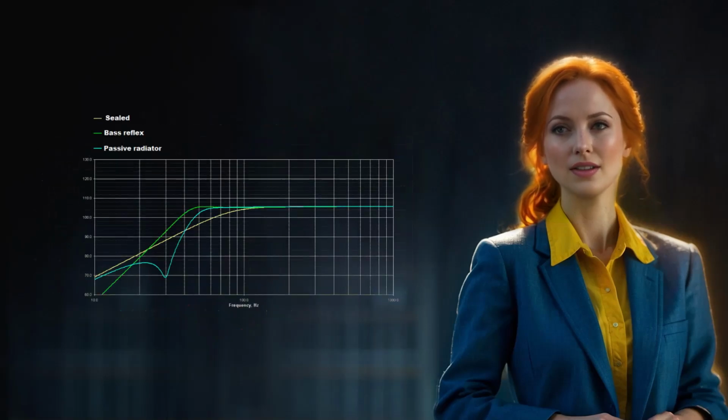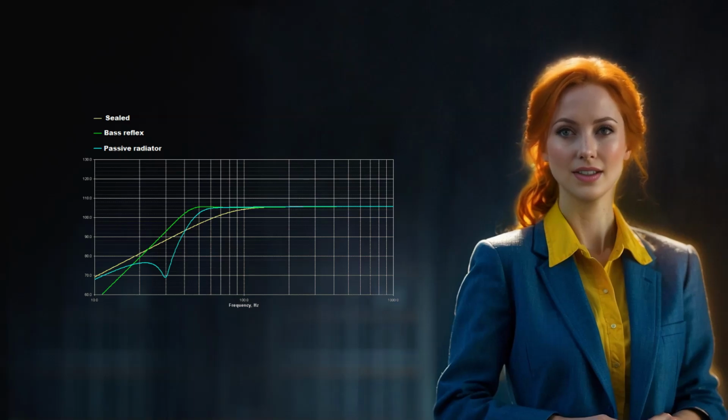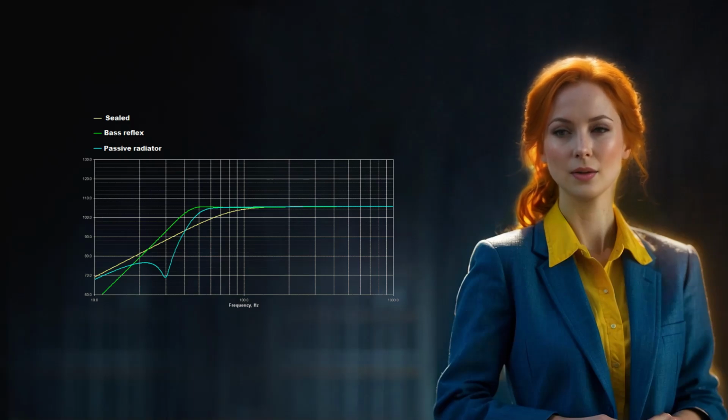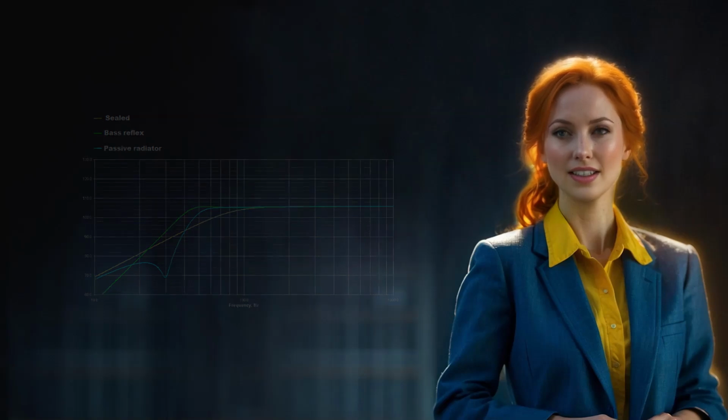As discussed above, the dynamics of speaker diaphragm vibration become complex near the resonance frequency. While the resonance can make the bass sound louder, it can introduce difficulties in controlling cone movement, leading to a booming and unclear bass near that frequency, particularly in speakers with ports or passive radiators, which are inherently more challenging to manage than sealed boxes.